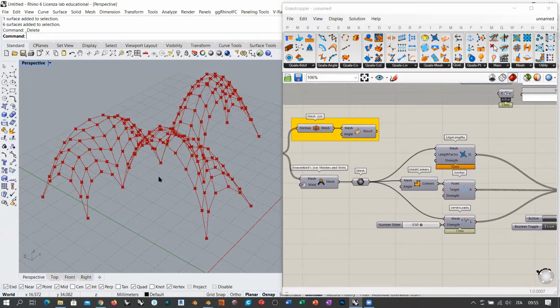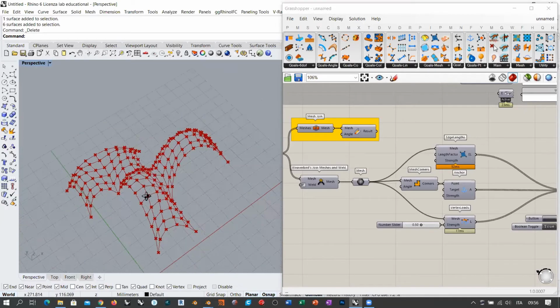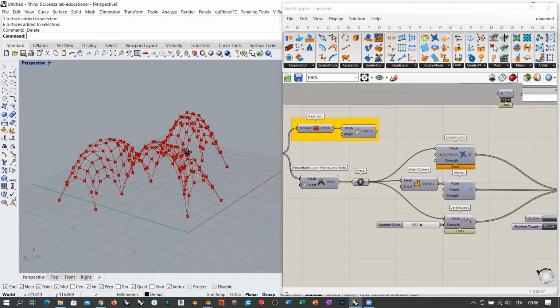If we consider that each of these springs has reached an orientation and a length based on load and elastic force, it means that it's only working with tension. And then it means that once you load this structure with the load that you are considering, this shape can easily bear that kind of load without changing shape. Okay, so that's what we are getting here right now.